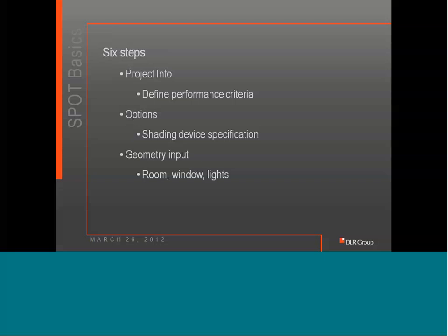The second step, this is an advanced step, and that will help you determine shading devices. Say if you have blinds, and if you can control those blinds, you can specify what angle those blinds should be calculated at. It can get a little complicated, so I would find most often I wouldn't get into this step.